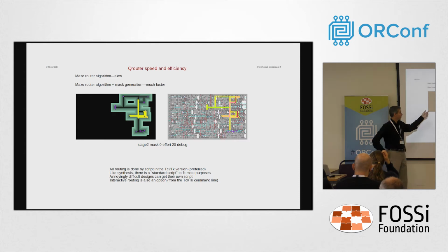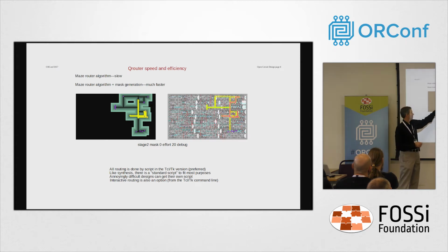It's based on, well, the original algorithm is what's called maze algorithm. It's a maze router algorithm, which you basically start at a source, figure out the cost of routing to any point in the design. You spread out over your entire design space until you find your destination, and then you backtrack over the lowest cost path. That's good for point-to-point routes. It scales very badly with size, and it's fairly poor. It does not give you an optimal route for a multi-node net.